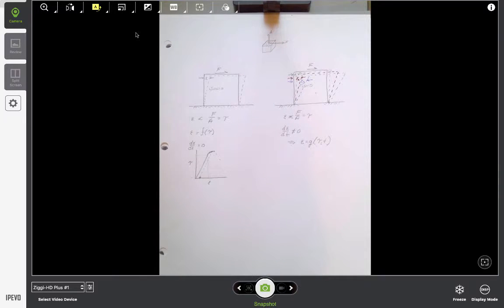The fluid deforms continuously as long as the stress is applied. The fluid will continue to deform. The strain is still proportional to stress. The strain is now time variant. So to stop further deformation, we have to remove the force. But unlike a solid, it's generally not reversible. Removing the force, the fluid is not going to willingly go back to its original position. So that's the difference between a solid and a fluid.